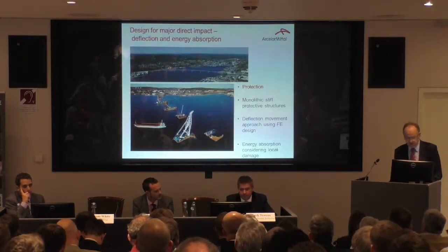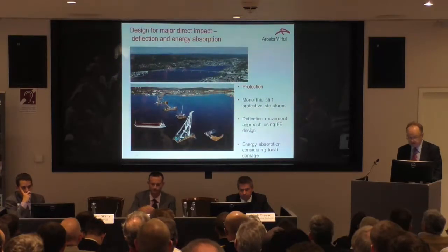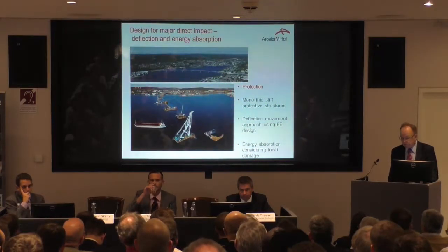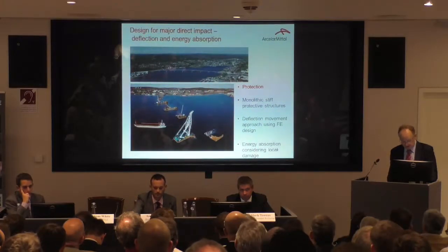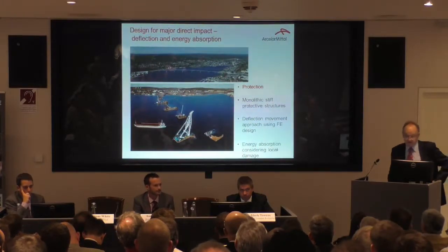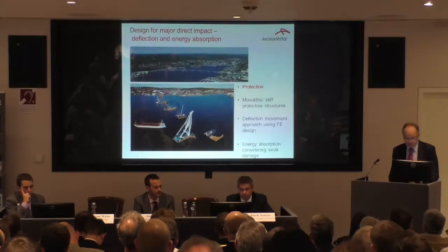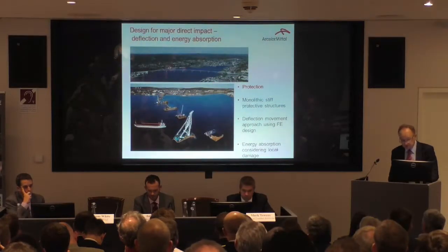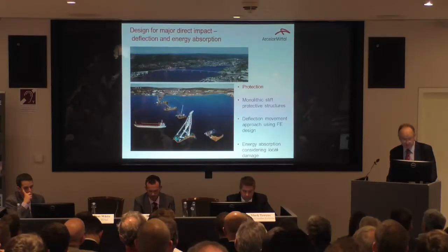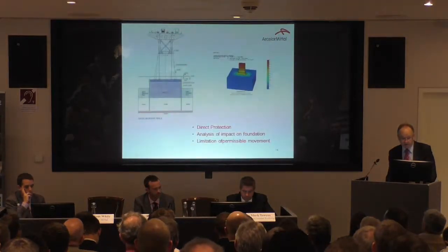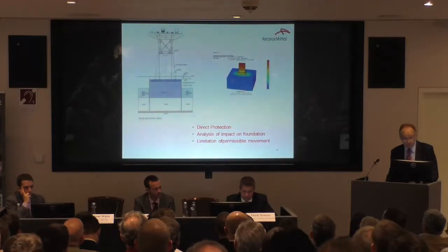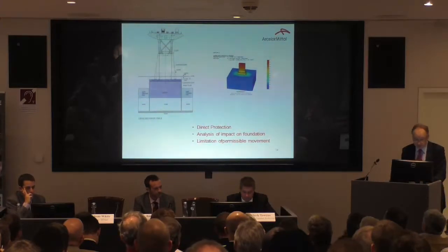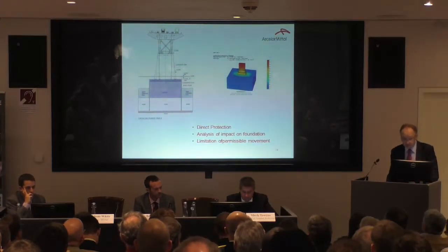So we can also design for direct impact, but usually this takes the form of rectangular cells. This is the Sundsvall Fjärdenbro, and there's a series of rectangular embedded retaining walls to form cells to protect the foundation of the bridge. So in section, the bridge superstructure is connected to the RC pile cap, which is tied into all the walls by tension ties.